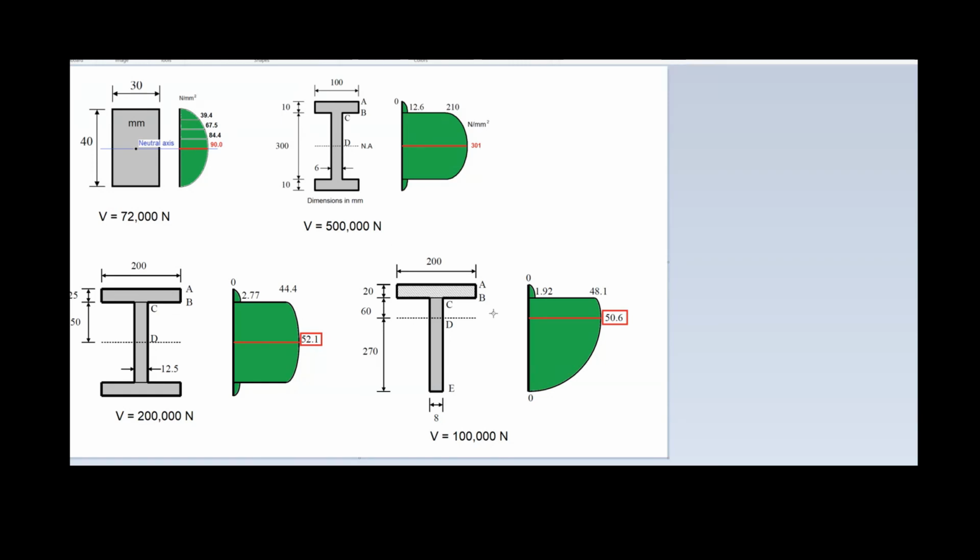the distribution is exactly the same as an I section, but from the neutral axis to the bottom of the section, of course, the distribution is continuous because there is no sudden change again in the width of the cross section. So it's very important to know what is the shape we're going to expect in terms of the distribution of shear stresses in order to have a simple calculation of the values and just connect the values with the appropriate curve, which is a parabolic function in this case. Okay.